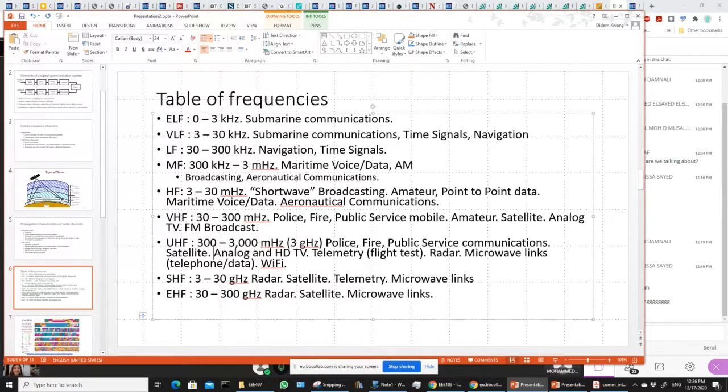But if you go up to 30 gigahertz, like 60 gigahertz, you could have a bandwidth of, not 10 gigahertz, but 5 gigahertz or 2 gigahertz. That's gigabits per second speed, right? So you can really improve your transmission speed by increasing your bandwidth. Each signal is given more space because there's more space in the higher frequencies.